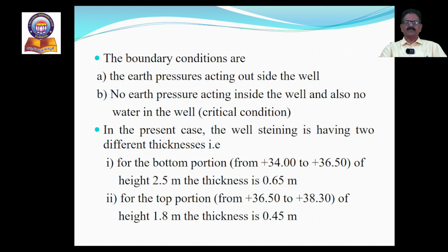For the top portion, from 36.5 meters to 38.3 meters level, a height of 1.8 meters, the thickness assumed is 0.45 meters.